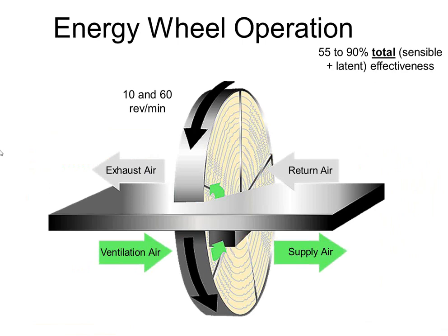Doesn't the wheel need to be dried? I'm not sure what you're referring to there, Dan, but I'm thinking you must be thinking of not a heat recovery application, but perhaps a wheel reheat application where you need to use a gas-fired heater to re-energize the desiccant material. That's not really an issue on this type of recovery, and we're going to go through that a little bit here.